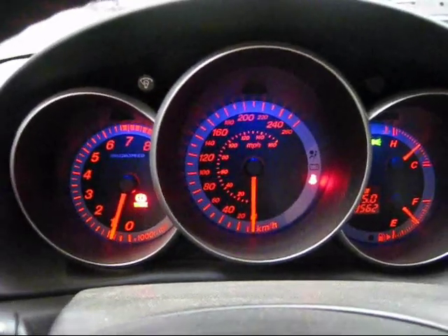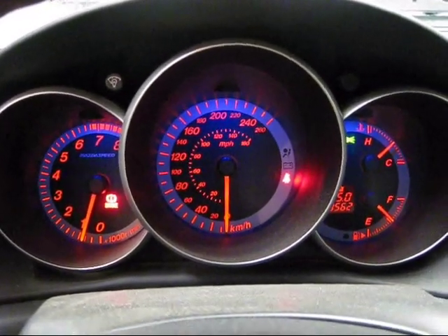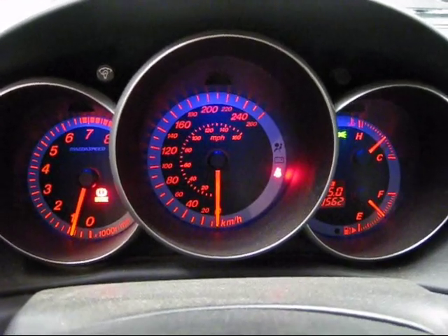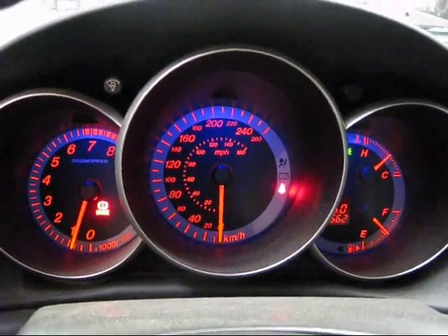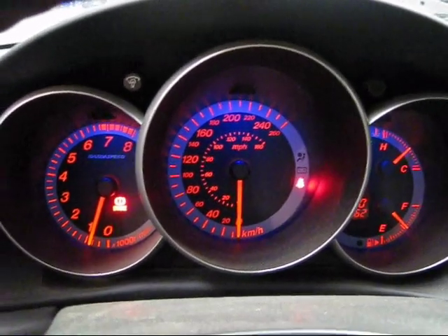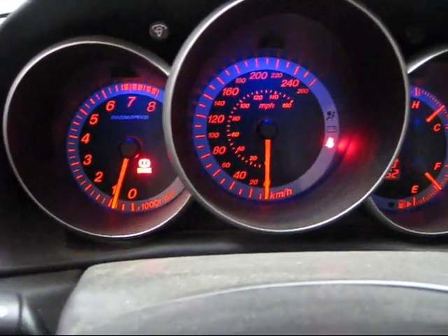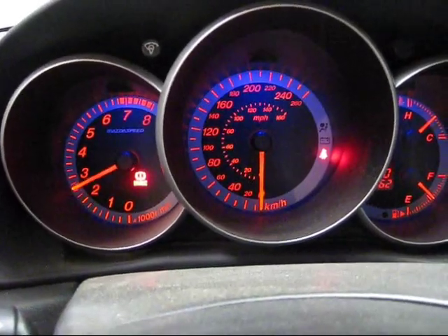So I just cut to after I reflashed my ECU with my map with the rev limiter for the launch control set. I just have it set at 2500 RPMs. You'll probably notice it's slightly less than the 2900 that I had set in the video. But just give her a go and it should work. You actually build a bit of boost.